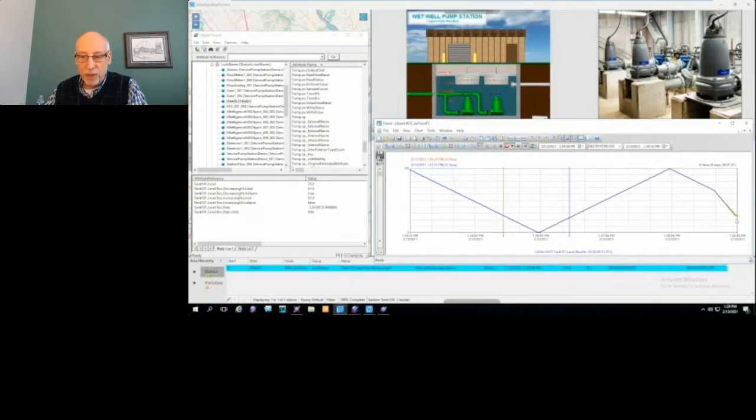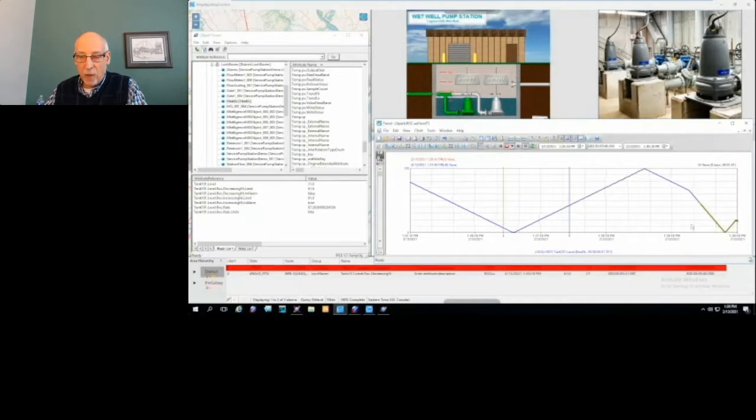The trend itself is highlighted in yellow, saying it's a high alarm. On the upward slope, we change that priority to be a high alarm, so it's going to be a different color. So when this goes in the upward slope, it's also going to start generating alarm. After that 10 seconds, it's going to wait for that. There it is. It just generated that high alarm, and you can see the color coding is on my trend chart indicating that that line slope has changed.